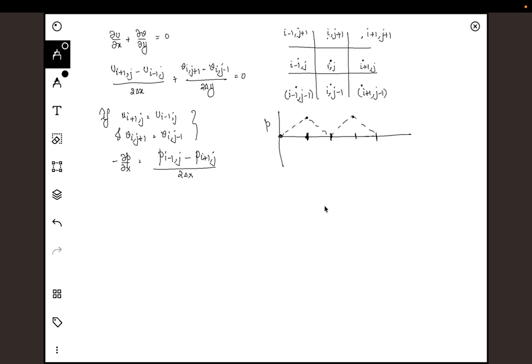But the way we have discretized it, if this is my ith point, in order to calculate the derivative at this point it will take p_{i+1}, this value, minus this value. This value minus this value is basically 0. So it will think the pressure gradient is 0. Then this gets propagated into the momentum equation, and the velocity will not be updated because there is no pressure gradient. And if velocity is also like this, then velocity will also not be updated. That is the main problem, which we call the checkerboarding problem.